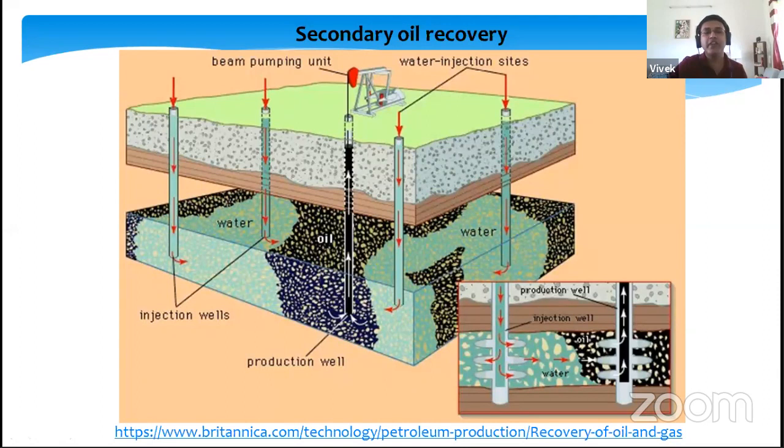There are also ways by which steam can be injected, steam generated by utilizing oil from the reservoir, and various other solvents, acids, and gases can be pumped in. Depending upon the type of oil and the pattern with which oil is distributed beneath the earth's surface, we use a different combination of secondary recovery options, which is going to recoup another 20 to 30% of oil.